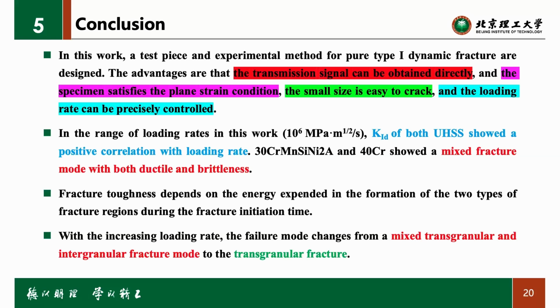And I showed the loading rate effect of the dynamic fracture toughness and the dynamic bending stress. And it should be noted that the fracture toughness depends on the energy expended in the formation of the two types of fracture regions during the fracture initiation time.